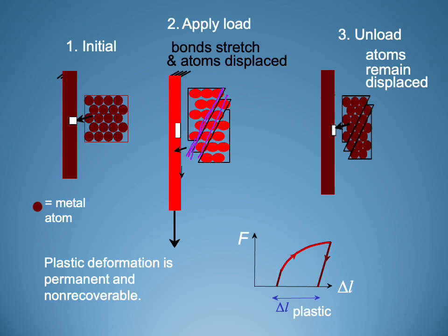So we've got this and that. So there's a specific plane and they're sliding past one another. That phenomenon, for lack of a better word, is called slip. And the slip is occurring on specific planes, depending on what metal it is, in specific directions.